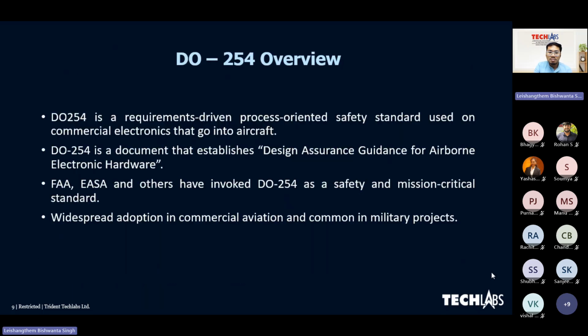Moving on, let me have a quick overview of DO-254 once again. DO-254 is a design assurance standard for airborne electronic hardware. It lays out a requirement-driven, process-oriented way to prove that flight hardware like FPGAs and ASICs does exactly what it should.